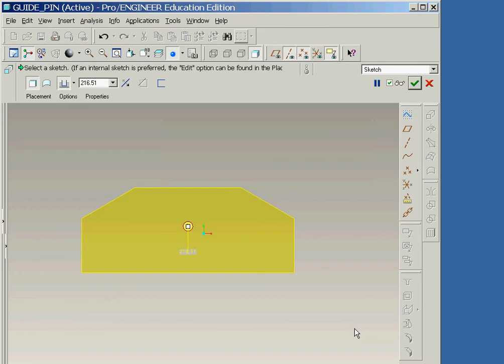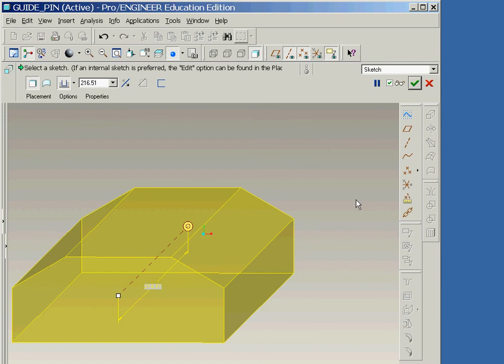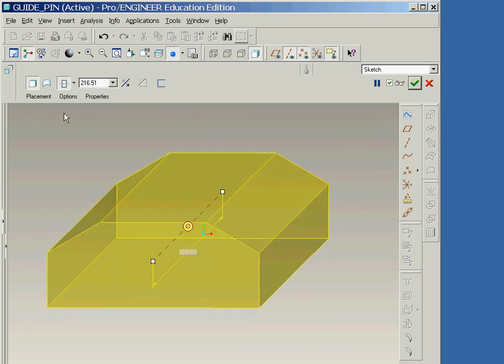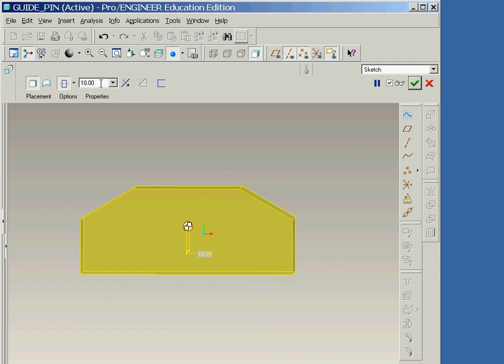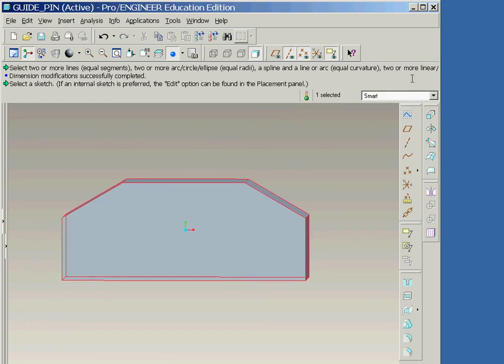And then, in order to improve the view of our protrusion, we'll now rotate the model. In the dashboard area, we'll change the extrusion direction so that it extrudes on both sides of the sketch plane. Next, we'll set the depth to be 10 units and then finally accept the feature. We will now add a revolved feature on the top of our base feature.